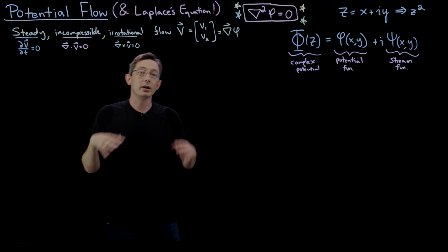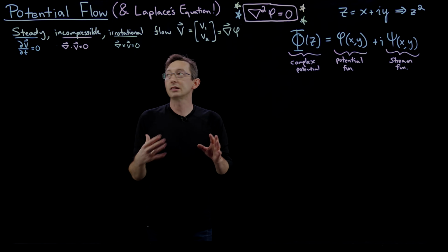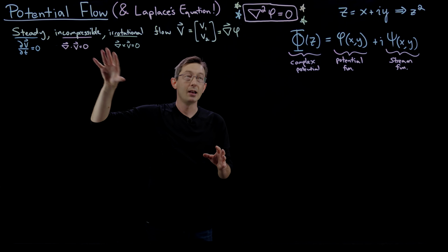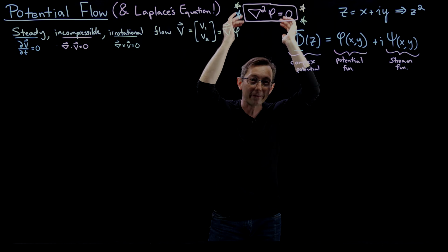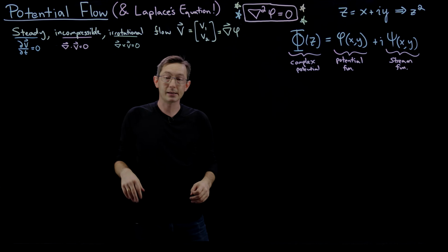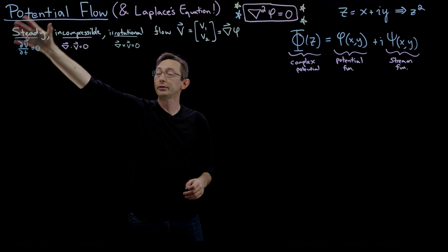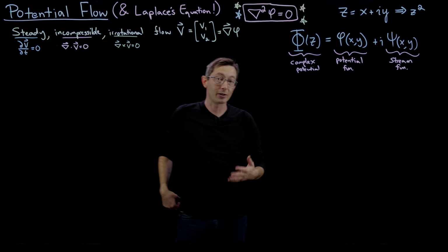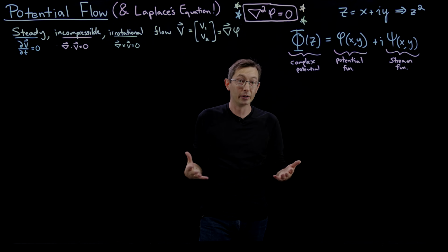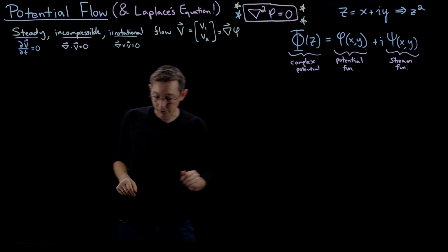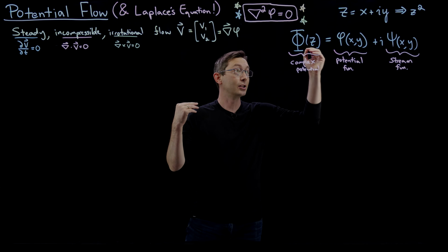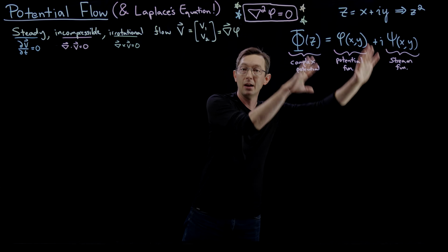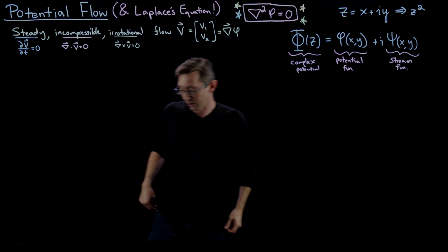And so today we're going to zoom in a little bit more and look at some of the properties of these potential flows, and some of the properties of Laplace's equation. This is one of the most fundamental PDEs in all of physics, and the resulting potential flow can be used to describe a lot of phenomena in fluid flow physics. Okay, so I'm going to jump right in, and I'm also going to give a couple of examples. We're actually going to use this complex potential function to derive some potential flows.